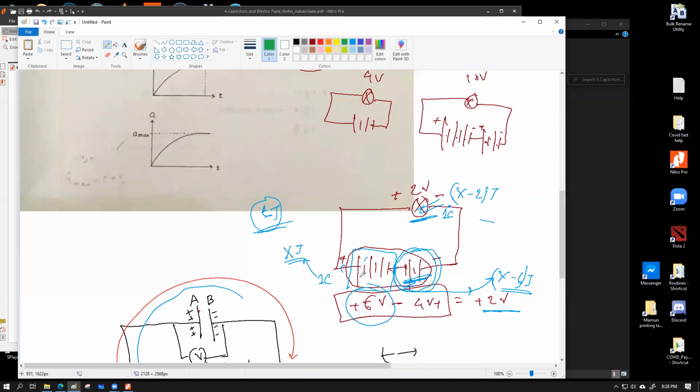Battery low means that the total amount of chemical energy that we started the battery with at the start of use is slowly going to be used up. In the example I've shown, for every 1 coulomb of charge that comes out of the positive end of the battery, flows through the external circuit and comes back to the battery once again, this battery is going to lose 6 joule of energy for each coulomb, because this has an output voltage of 6 volt for this circuit setup. Which means if you keep this circuit on, this battery is going to be continuously losing energy. Each coulomb of charge is going to lose 6 joule of energy.